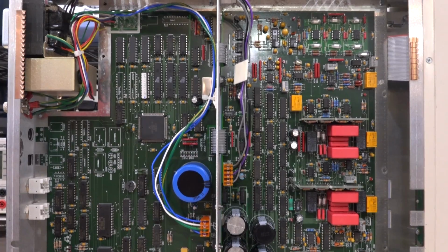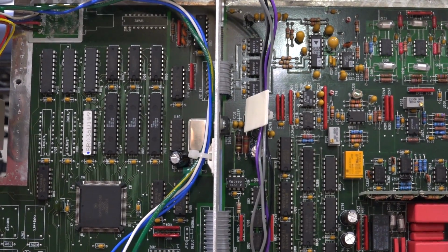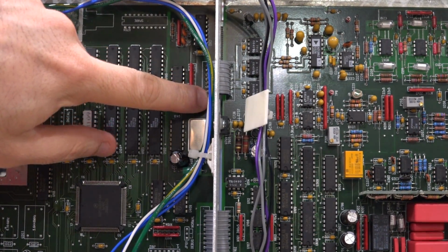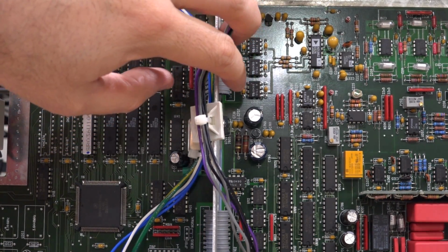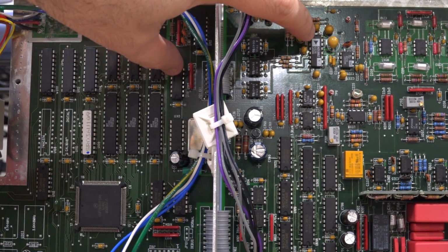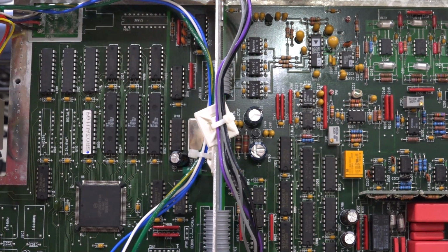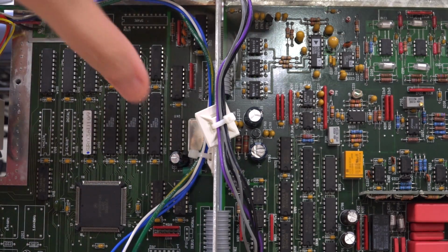And looking a little bit closer at the top side, we can appreciate what's going on. This guy over here goes through these three optoisolators. These are really fast optoisolators and low jitter, and they feed our primary DAC. That's the DAC I was talking about. This is an AD1862. So you can look up the data sheet of that one.